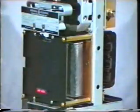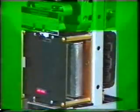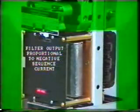The presence of these components provides a useful tool for detecting unbalanced conditions and ground faults. For protection, both zero sequence and negative sequence relays are installed. Typically, the negative sequence relay works by comparing voltage or current in all 3 phases and filtering out negative sequence components.